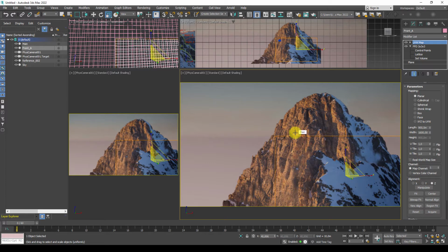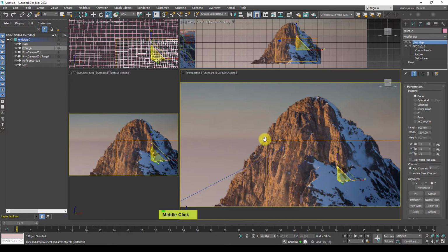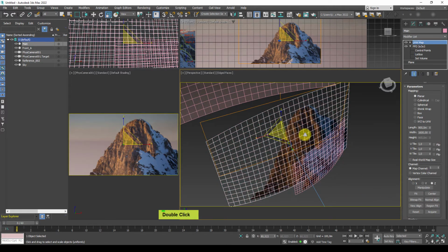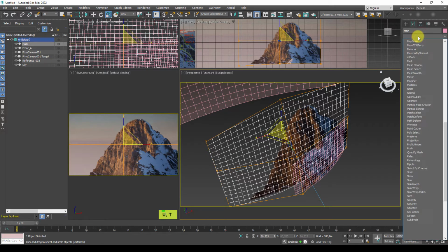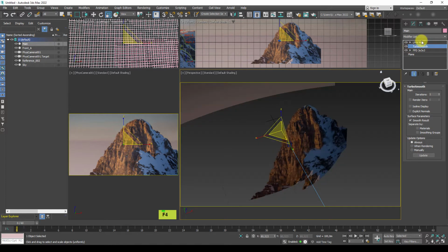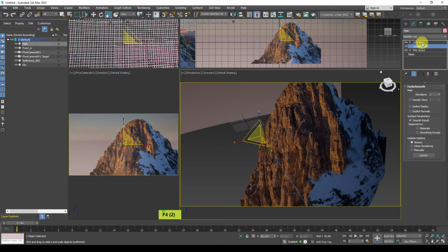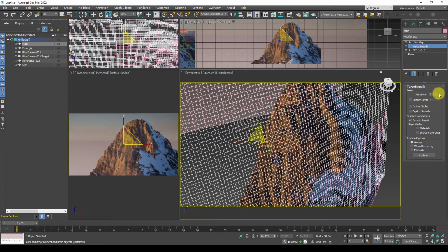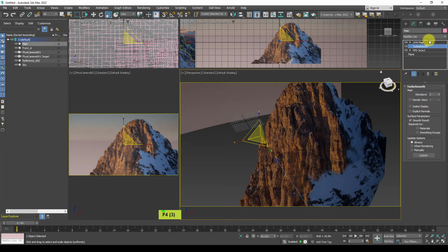Now what else? So before we go on with the different layers, let me go perspective and share something with you. Now we can go further. We can actually sculpt on these, but it's not a necessity, so you don't have to do it. What you can do is apply a turbo smooth under the UVW map. UVW map is always on top because that's our crucial point. And turbo smooth divides your model even further. So maybe 2. Okay, when we have geometry that's a little bit more detailed, we can apply displace.